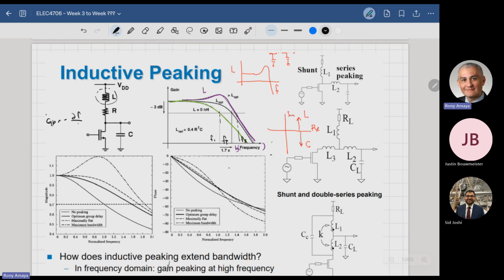So you can have maximally flat amplitude. Which one is maximally flat amplitude? Butterworth, yeah, right. And then you can have a Chebyshev as well, which is kind of a ripple effect on it, but you can improve the selectivity. The problem with maximally flat amplitude is that the selectivity is not so good. So if you want to make it do a sharp turn at the end, you do something like a Chebyshev. But neither one of those is good for maximally flat group delay.